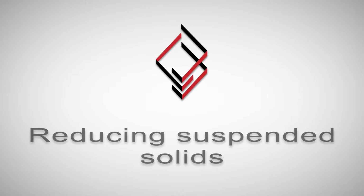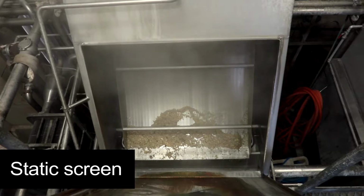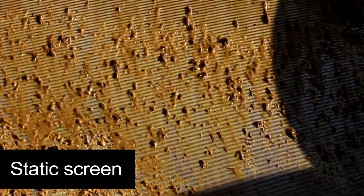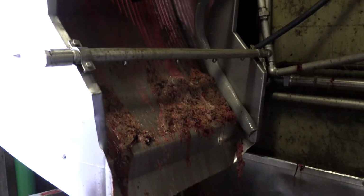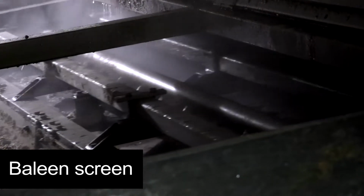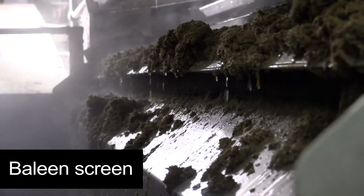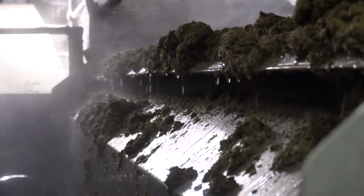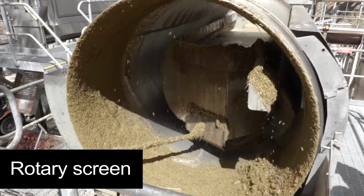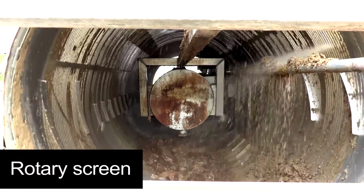Technologies used for reducing suspended solids levels include static screens, which are vertical bow-shaped screens that have no moving parts. They're usually made of a wedge wire screen to reduce blockages by fine solids or fats. A more recent innovation is a baleen screen, where the screen is a fine flat screen which slopes slightly. A mechanical water spray arm pushes the solids away from the filter for disposal. Rotary screens have a rotating horizontal cylinder. The wastewater enters either inside the cylinder or on the outside top of the screen. The solids are moved to the opposite end to be discharged.